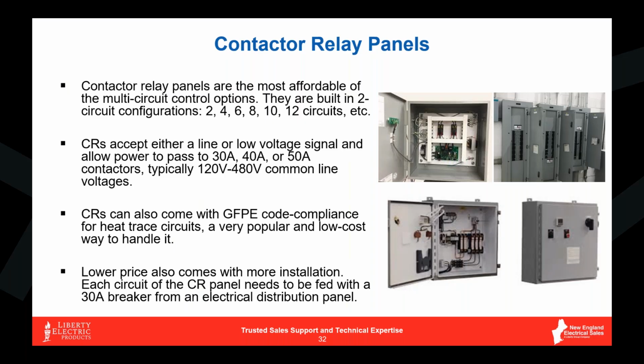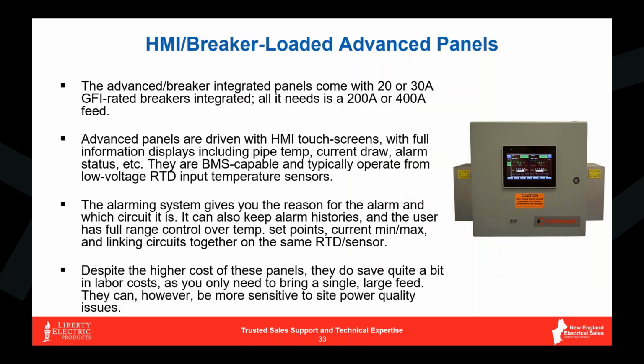I mean, again, it kind of depends on the application, the end user, what are they looking for out of the system? So, being that these contactor relays also have GFPE compliance with them, this is oftentimes a much more affordable way to handle that code requirement versus going out and finding dedicated GFI breakers. So again, it's a little bit more work with these because you have to wire each circuit individually over, but very versatile, very affordable. We have tons and tons and tons of contactor relays out there. And it's by far, I think, the most common multi-circuit controller out there.